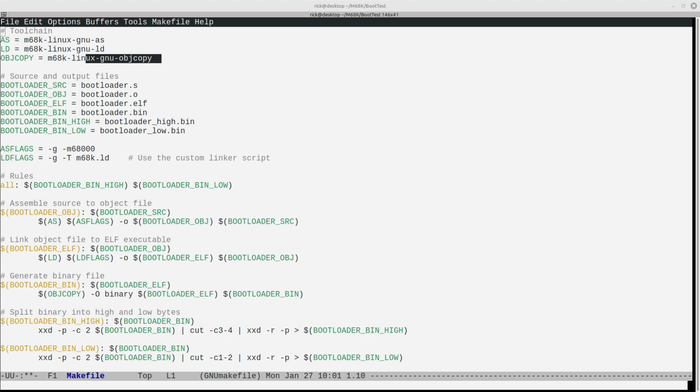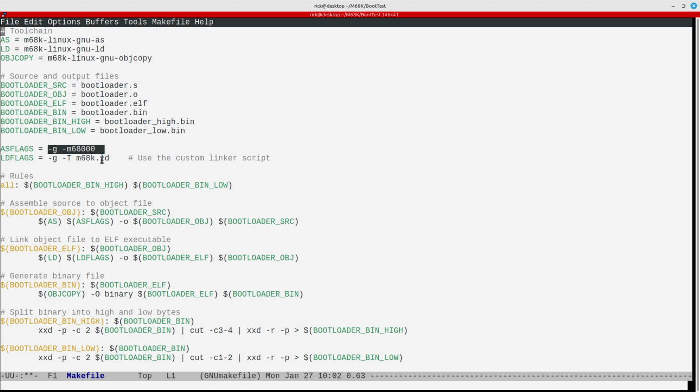So it supports the full M68K instruction set. It includes various addressing modes like direct, indirect, and immediate addressing. It allows directives like .section, .global, .equ, and others for controlling the layout of your assembly code. And it allows embedding of debugging information when you're using the -g flag. So when you're working with the toolchain, it's not standalone. You get all of the other stuff for assembly, linking, and binary manipulation.